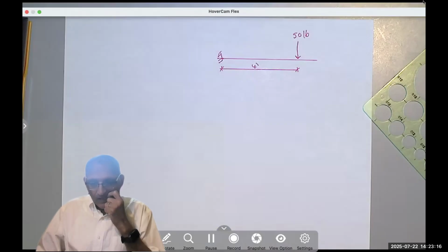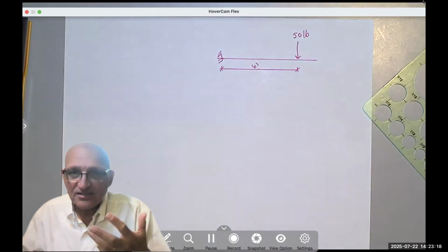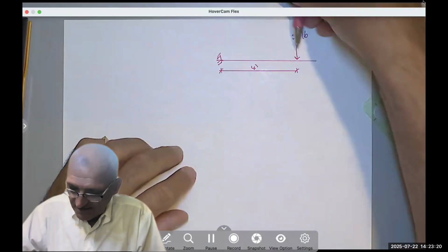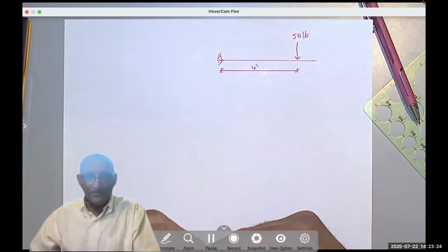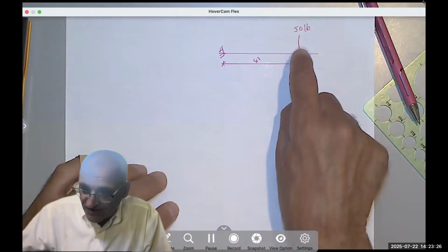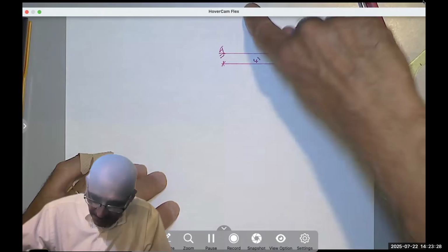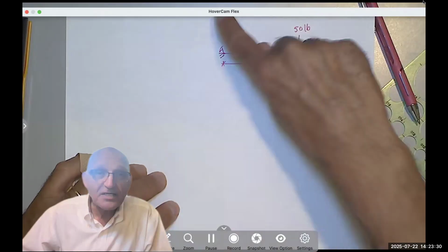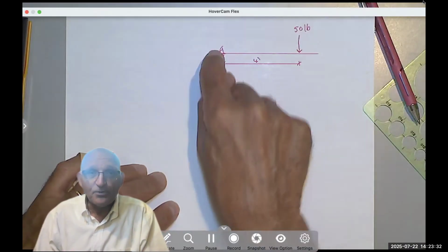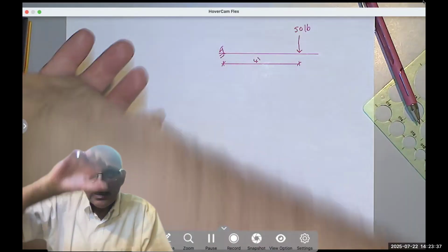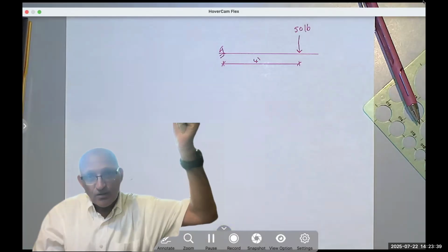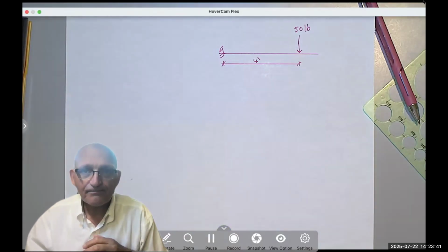Usually you can see, later you will learn that, since this is pushing down, the whole thing is being pushed down by a force of 50, right? But this force is also producing rotation, a moment, a clockwise moment about this support. So this support is feeling a force pushing it down, and something wants to rotate the whole beam clockwise.